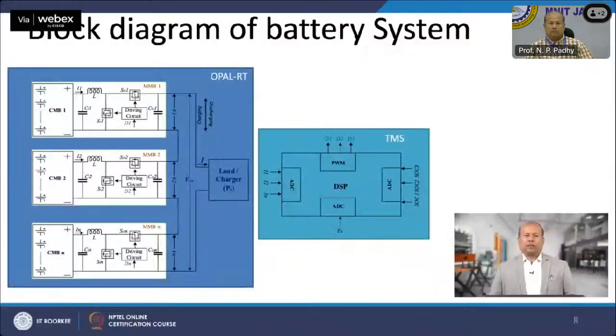The SOC balancing algorithm is developed based on the average standard deviations. By comparing the SOC values with the mean values, a balancing factor is determined for all the 3 batteries in a similar way. Using the balancing factor, the power is shared among the battery modules accordingly. By using a PI controller, the bus voltage is maintained and PWM signals are also generated.